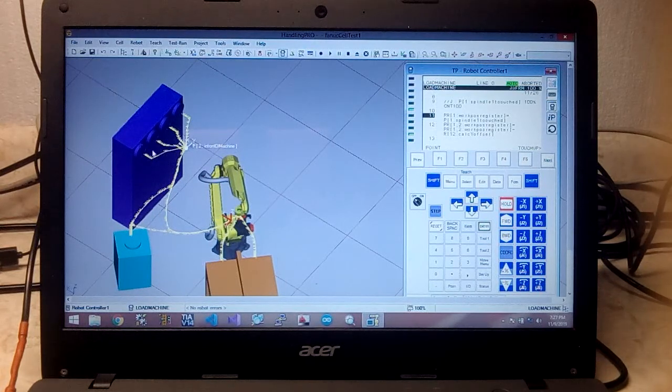Because this is parametric, I'm using a PR, and the PR takes the value of the current point and is offset by the amount on Y. So this here is axis Y. So I run this, the machine is aligned with the y-axis. So from spindle 1 or fixture 1 to fixture 2, 3, and 4, that is 250 millimeters between centers.